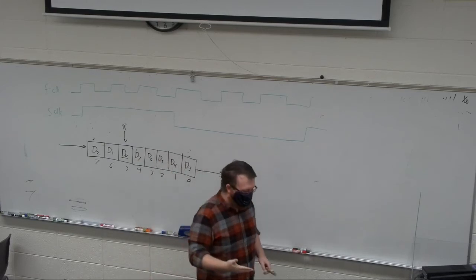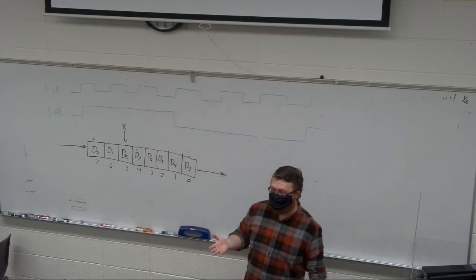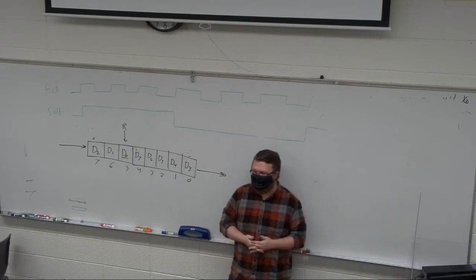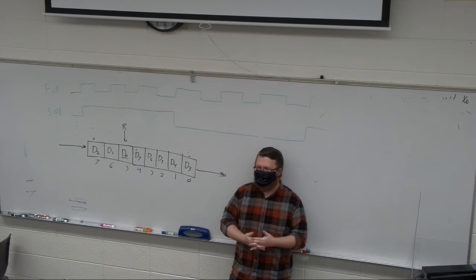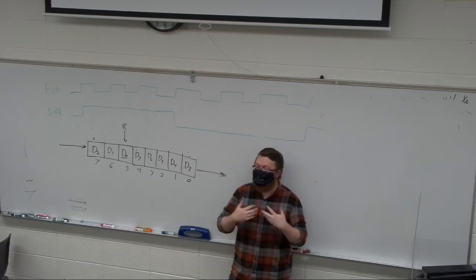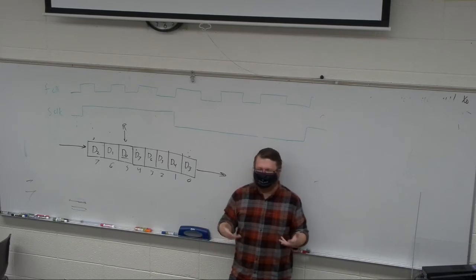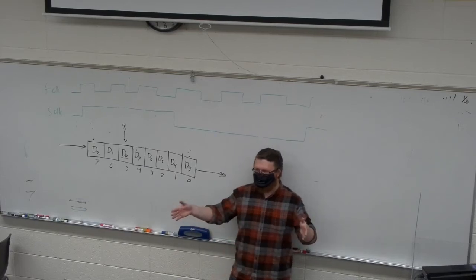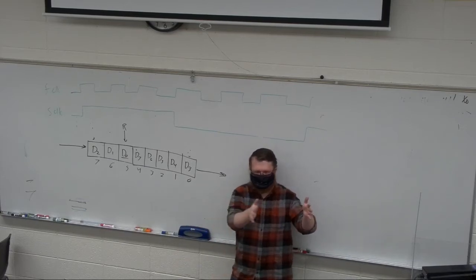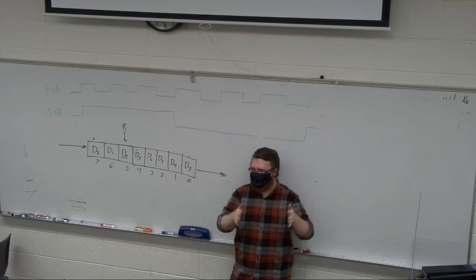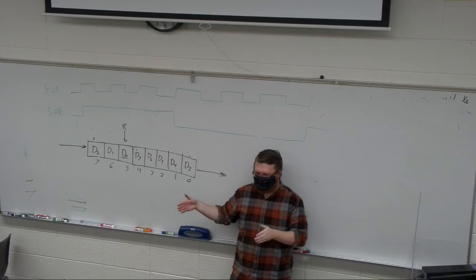But let's say we have an ADC that's generating bits at 200 kilobits per second, and we're transmitting that data output over a UART at 100 kilobits per second, right? So that ADC is going to have a backlog. We're going to know that we have a limit to the amount of ADC data that we can read that is dependent upon the FIFO storage. Because if that FIFO overflows, we have a problem. So we can read and then wait as it empties out over the slow bus, and then read and then slowly empty it out, right? So we can record in kind of bursts.